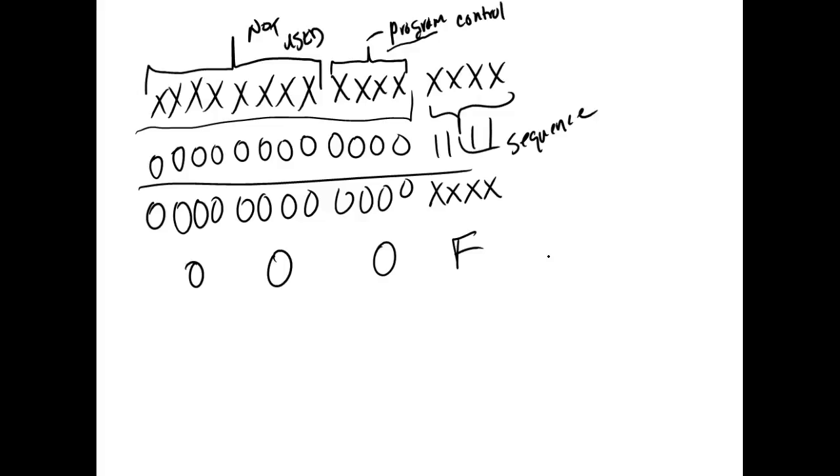Yeah. So normally your move with mask, your mask move, and your sequencer use an AND mask. The MVM, which is the mask move. Since it's MVM, it pops in my head as move with mask. I think the book calls it the mask move. It uses an AND mask, and the sequencer output command uses an AND mask. If you want everything to come through, then you'd use all Fs, right?